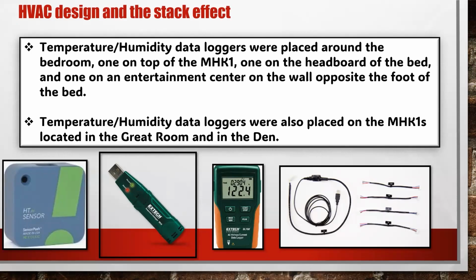But in the one-way ceiling cassette units, because they're enclosed in an insulated box in the ceiling, I've seen those things do the overheat protection scheme every 5 minutes in some cases. And that can easily overheat a room. But maybe even more important to offer two systems in a house, if that's what you're planning to use, is those one-way ceiling cassettes.